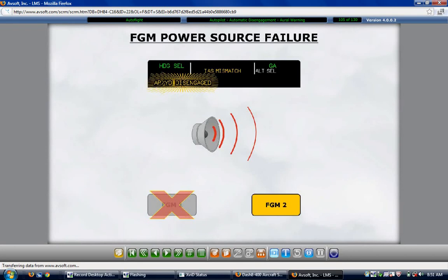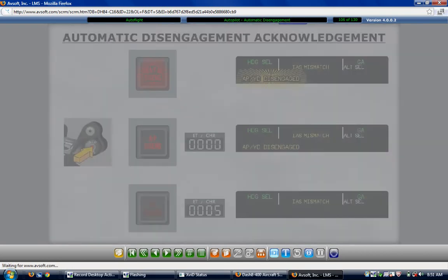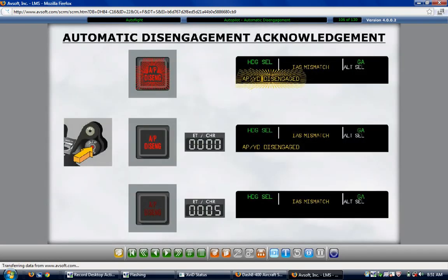When the autopilot is engaged, it commands pitch trim to reduce the mistrim control column force held by the autopilot pitch servo. This ensures that the pitch will not jerk when the autopilot is disengaged. Active tactile control steering use temporarily disables the autopilot pitch trim function.